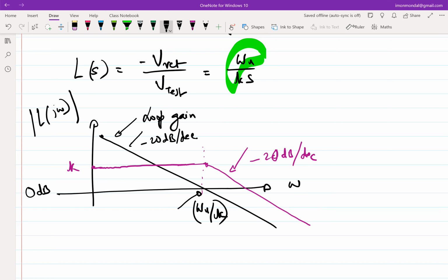What I'm trying to get at here is whether, by looking into the open loop transfer function or loop gain, we can get a feel of what the closed loop transfer function or the closed loop plot will look like. And why do we want to do that? Because for the purpose of analysis, it's always easier to analyze something in open loop than in closed loop. This is firstly a first order system. Later on, you will see that you have higher order systems. In that case, analyzing something in closed loop becomes slightly trickier. However, if you know where to apply the input and where you are taking the output and nothing comes back and changes the input, if it's in an open loop fashion, then it becomes far easier to deal with those transfer functions and draw an analogy from there.